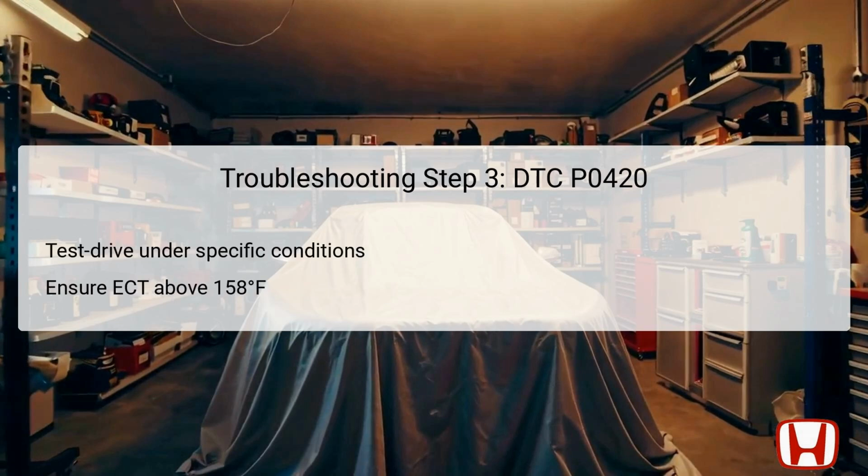For the third troubleshooting step, you'll need to test drive the vehicle under specified conditions. Start by checking that the engine coolant temperature, ECT sensor 1, is maintained above 158 degrees Fahrenheit, 70 degrees Celsius. The vehicle should be driven at speeds between 45 to 75 miles per hour, 72 to 120 kilometers per hour, for at least 5 minutes with the cruise control set.